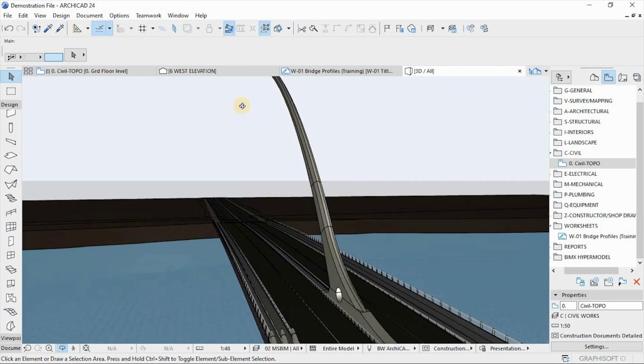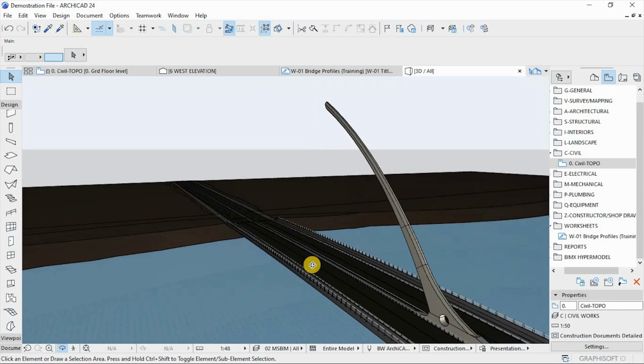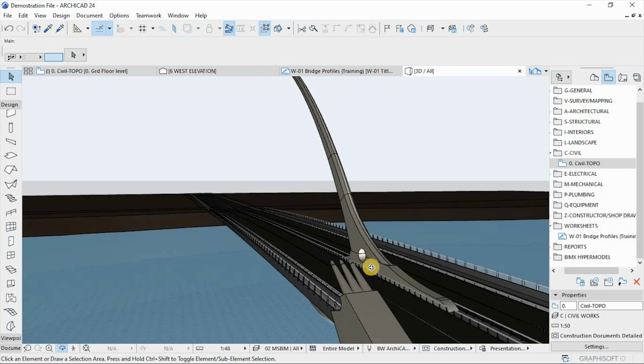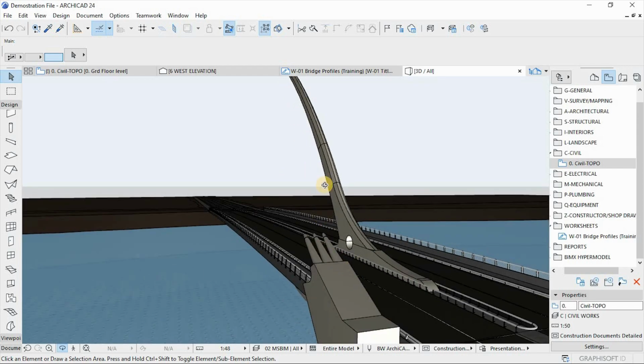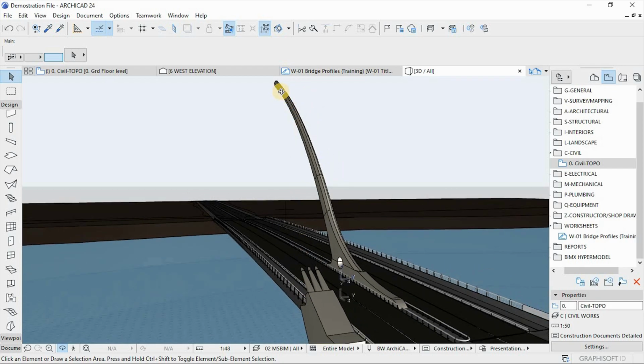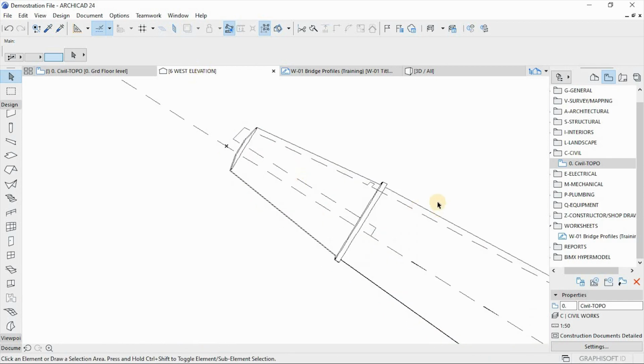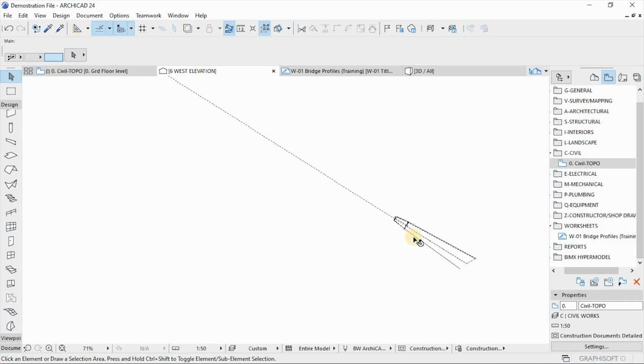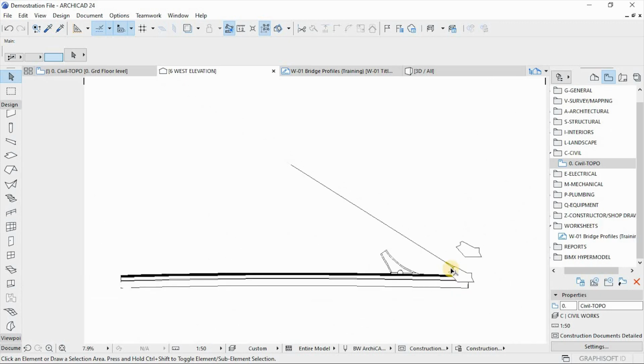And then we ultimately are going to rotate. Sorry guys, let me find a perfect view. Ultimately we're going to rotate these three guys so that they can be in line with the suspension clamp that is going to be fixed here on the tension feature column. So the best way is to create first the clamp here. So go back to the elevation, and then we're still going to use a move tool again to create that.